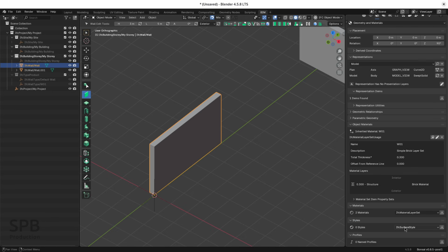For us, this will be IfcSurfaceStyle because it's the surface color. So it's important to note that the material, the brick material that we created, does not define the appearance properties of the object or the material. And the appearance properties are defined by these surface style, either surface style, fill or fill area style.